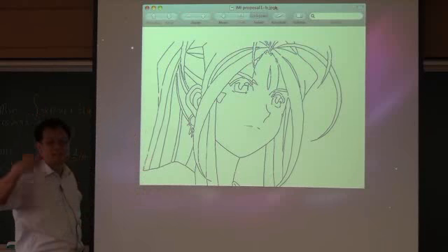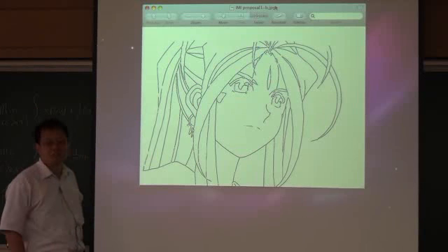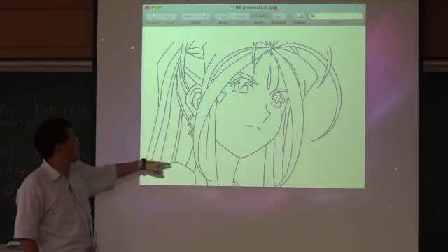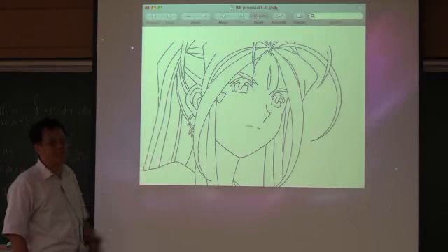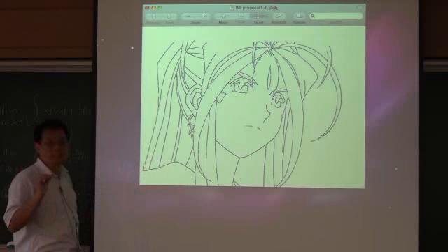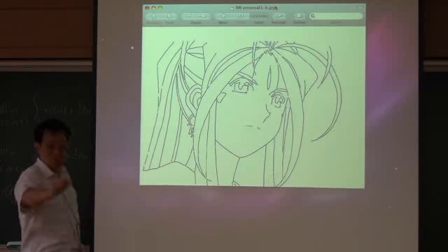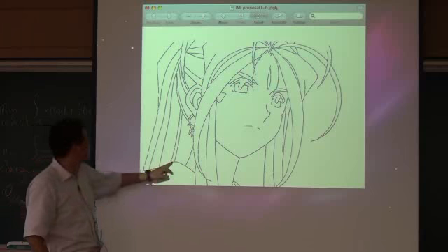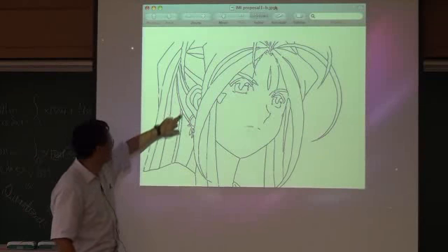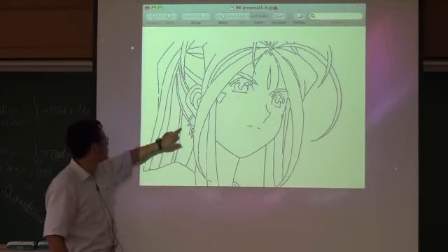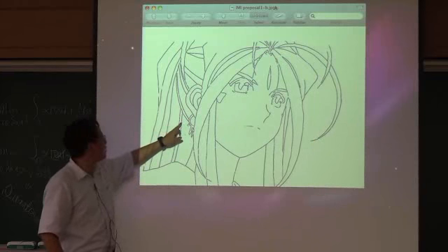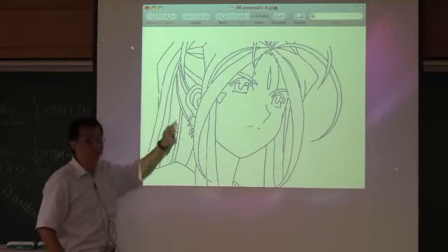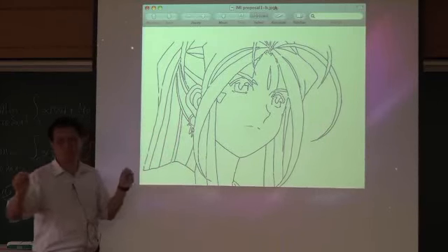That's the first thing you do if you want to computerize. So essentially, vectorize the curves. At the moment, it's mostly still done manually, which means the person is sitting there, dragging the mouse, and you mark the start, mark the end. There's a computer program, and the computer does a B-spline interpolation, finds the middle points, and puts those points into the vector.